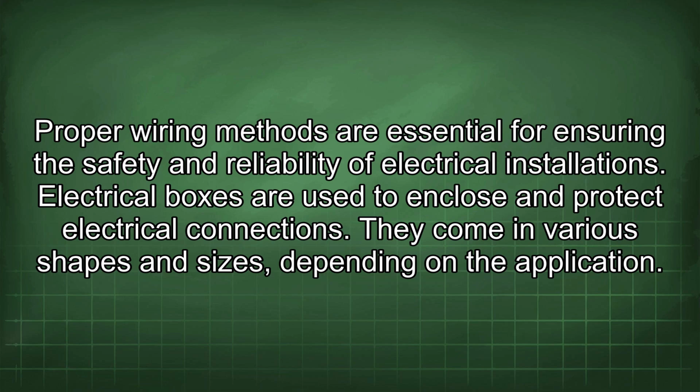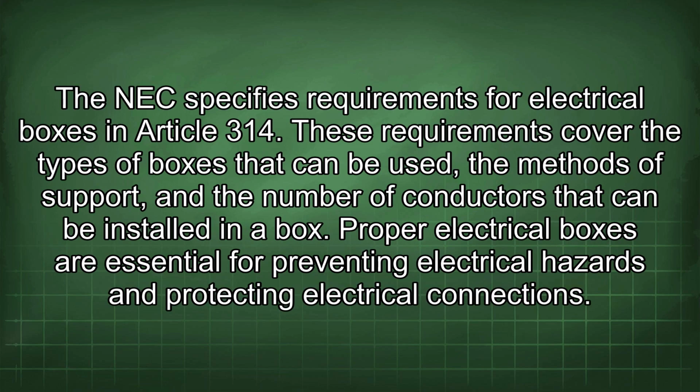They come in various shapes and sizes depending on the application. The NEC specifies requirements for electrical boxes in Article 314. These requirements cover the types of boxes that can be used, the methods of support, and the number of conductors that can be installed in a box. Proper electrical boxes are essential for preventing electrical hazards and protecting electrical connections.